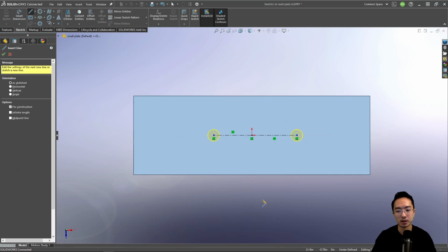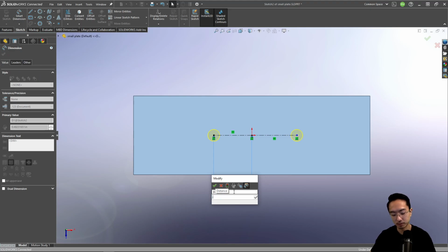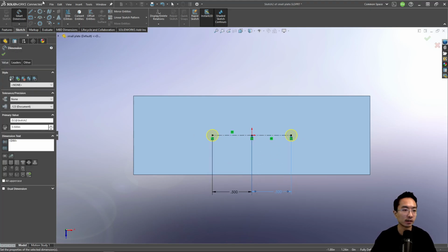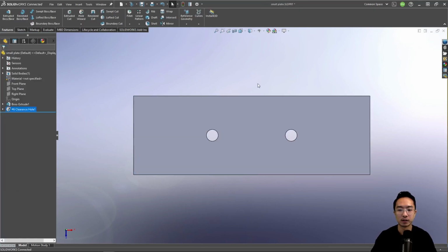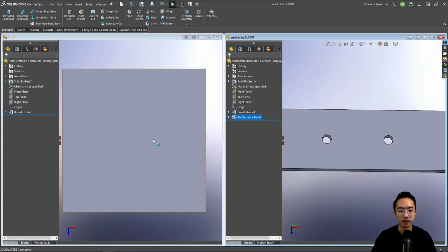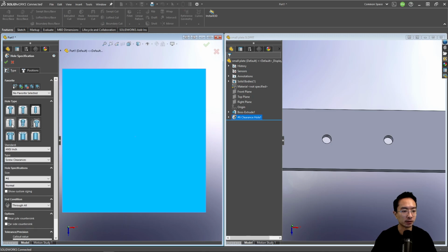and the 2 holes might be, let's just choose some arbitrary size, maybe 0.5 and 0.5. So this is the number 6 clearance hole. And maybe on this plate, we're trying to mount this little plate on this big plate. So here, we're going to also add a hole wizard. In our hole wizard, we're going to choose straight tap number 6-32.